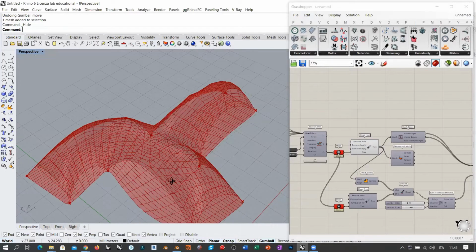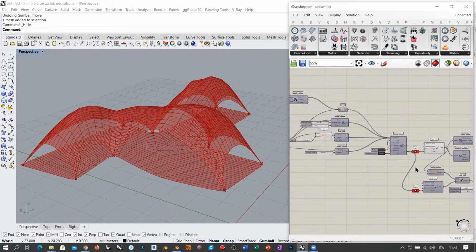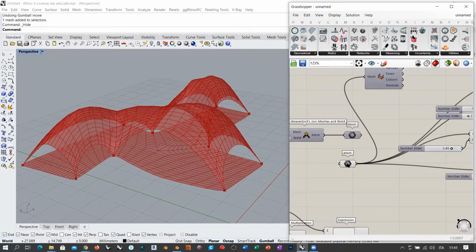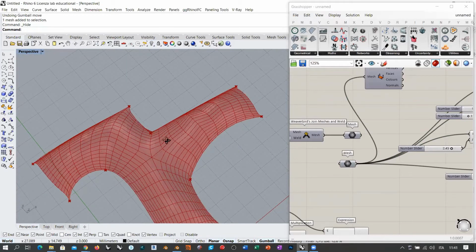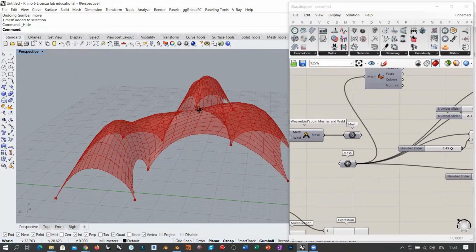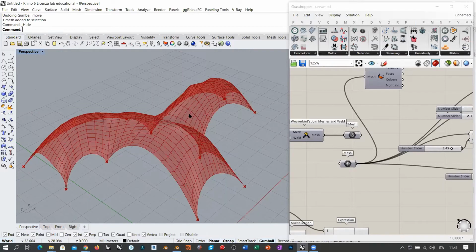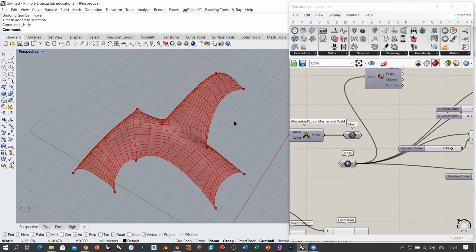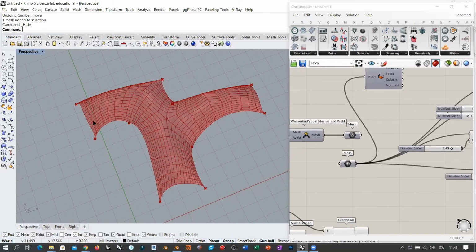Now you see that the deformation is occurring, of course, but you might notice, let me also hide the original mesh. Okay. The different topology that we are using is actually determining a different deformation for this object. So the topological editing that we did in Blender not only is useful if you want to create this kind of different loops flowing along the mesh, because eventually you want to distribute some kind of oriented geometry or oriented panels along these loops, as we did 2 days ago. But it also has some effect as regards the deformation, of course, because remember that the mesh topology is what generates the elastic property of this body.